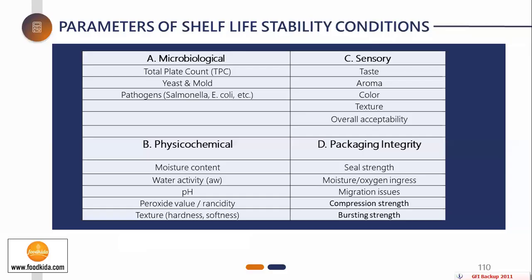Sir, what you just mentioned is for rotogravure printing only, right? And not for sticker packaging, not for stickers. Yes. Then migration issues, and then you have compression strength and bursting strength for your cartons, the secondary packaging. We will also discuss that, how you factor in the compression strength for your cartons.